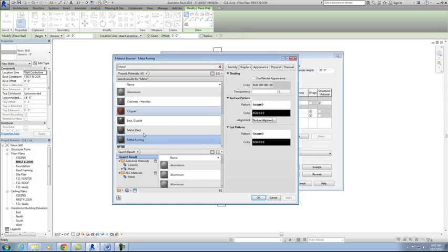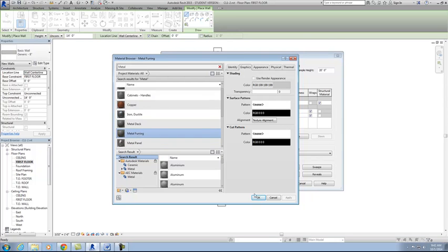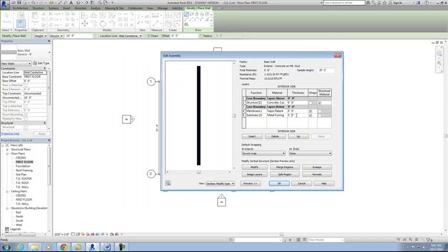And there is a level or material already preloaded. And we'll set that one to this thickness, which is 7/8 of an inch. And then finally, we'll insert our last one. Make sure they're all in the right order. This one will be our finish layer, so I'll stick with finish 2. And this will be gypsum wallboard.